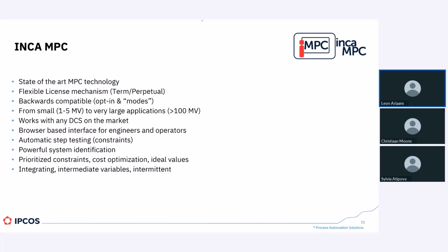If you have a flow that goes into a vessel and another one coming out, if the two balance each other, the level is going to stay constant. But if you increase the inflow, you will see that the level in that vessel is going to rise with a constant speed. That's an integrating CV, and it takes special configuration, special tuning to handle that case.